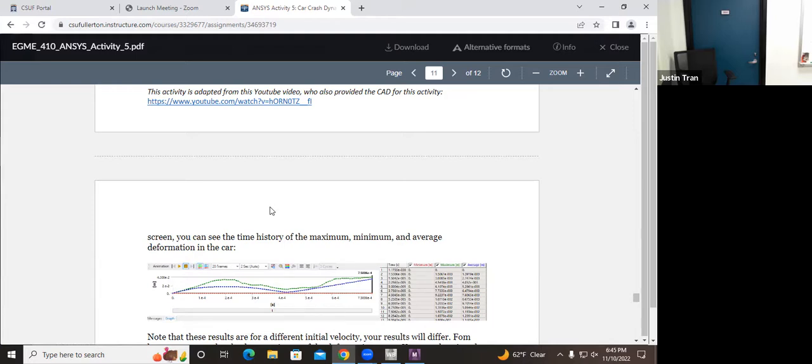Right. So 3 is basically you're going to manipulate these two so that you get TCS up top and PCS on the bottom. Remember, these are transformation matrices. When you multiply two transformation matrices and their inner dimensions agree, they cancel out. If you look at the answer of part 1, you have MAB R TCS, and for part 2, you have MAB R ACS. So they both have MAB, and you want to multiply them in a way that the MAB cancels out. The problem is MAB shows up on the left.